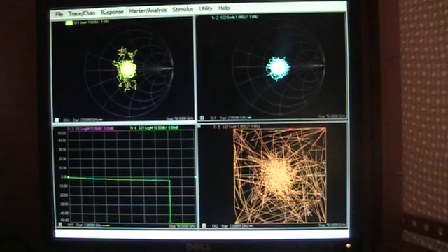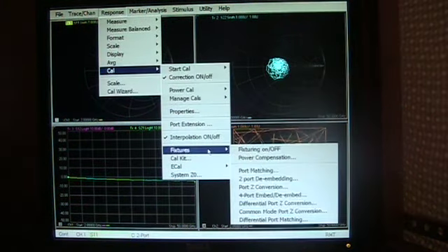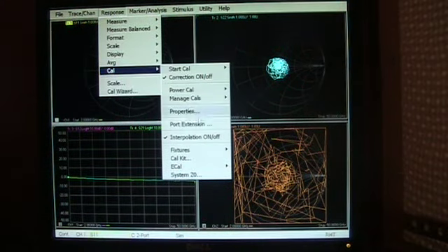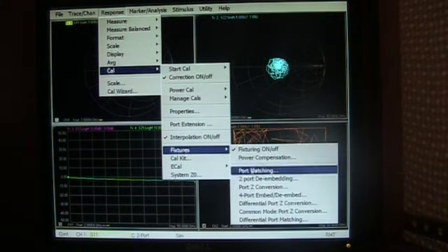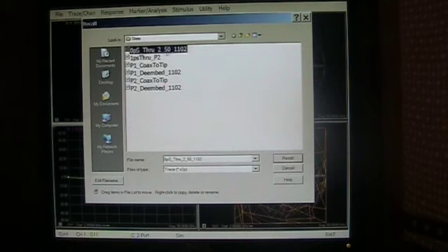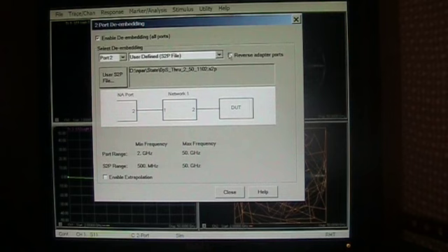So I'll select channel 1, I'll say response cal fixturing on, response cal fixtures 2-port de-embedding, enable de-embedding port 2 only, use the file 0 picosecond through from 2 to 50, November 2nd, and reverse the adapter ports.